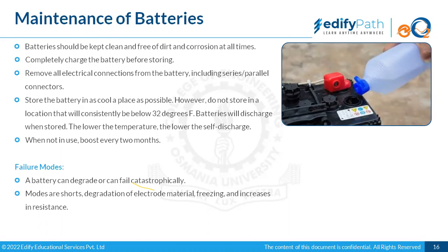Okay, so the condition that we call deep discharge. What happens is, if the lower cutoff voltage of a battery goes below that voltage, then we will call that deep discharge mode. So it won't start charging immediately when you put the charger. We put the charger, it will not start charging. So what we have to do is lift that voltage at least up to the lower end voltage, so that normal charging can start.